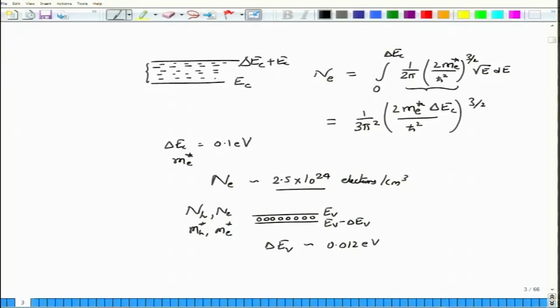The implication that electrons have a smaller effective mass also means that when you forward bias a junction, electrons will move quickly because of their higher mobility, lower mass, into the hole region, and therefore in most cases it is desirable to pump electrons from the N layer onto the P side layer.